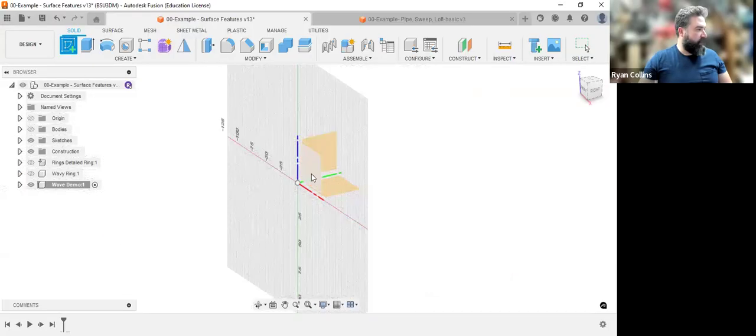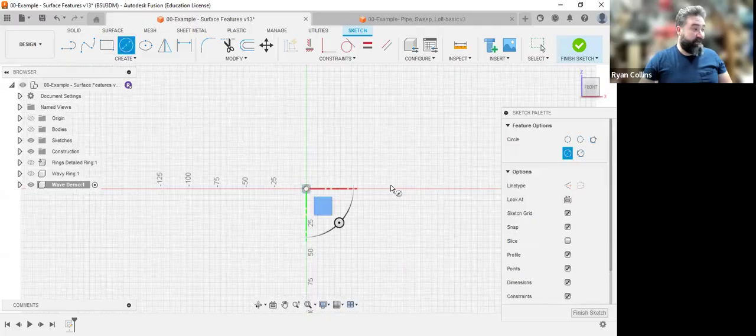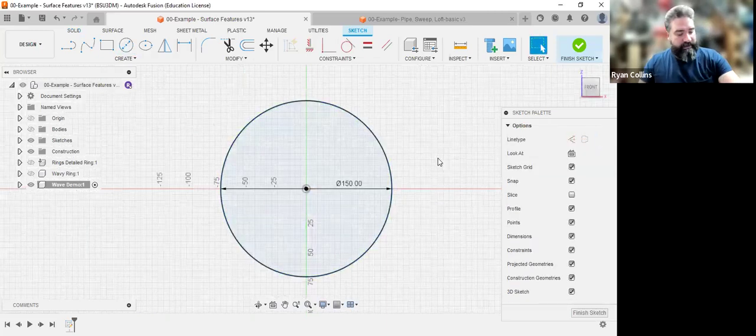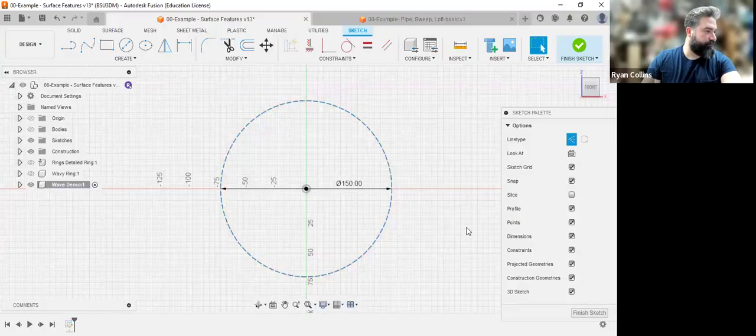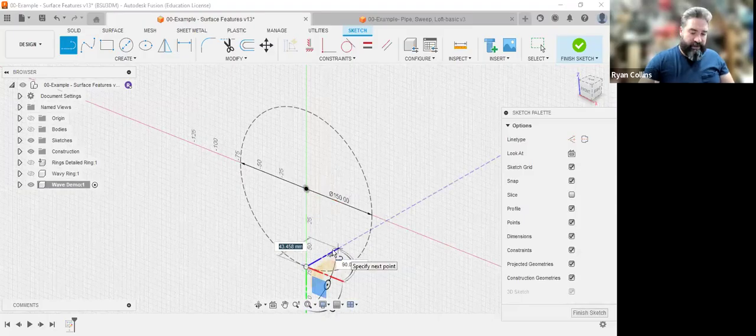All right. Starting again, center, some sort of circle that's going to be my reference point. Again, references are always helpful with this. I'm going to turn that into a construction line, press X. There we go. All right. Now we're trying to create something that's a bit different. So again, 3D sketch, line. I'll start at the very bottom because the question was to go more outward this way. Let's just say 20. Okay.